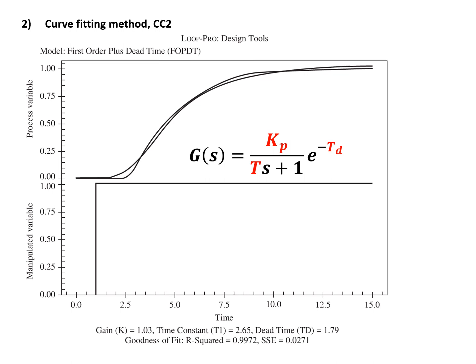Okay. To use a second method, you can curve fit the values using software. You can use the Loop software and so on. Try to curve fit the response that you get into this equation that is supposed to be first order with delay time. Normally this equation will give you the sigmoidal shape because you have a delay and it is roughly a first order system.